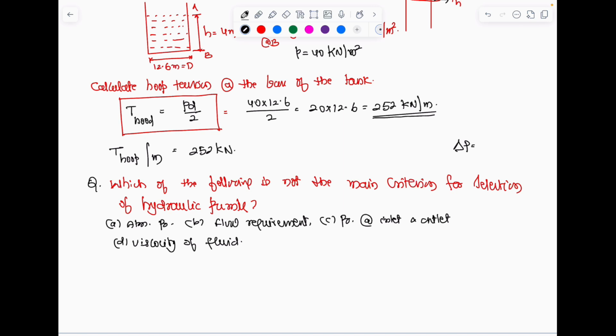And gauge pressure, the pressure with which the hydraulic pump is required to pump the product so that it reaches a certain part of the agriculture field where it has to pour the water, is required. Viscosity: the viscosity of water is lesser when compared with the viscosity of thick fluids like bituminous ones. That means viscosity is a requirement, pressure is a requirement, flow is a requirement, but atmospheric pressure is not a requirement, only for the reason that atmospheric pressure can be a datum.